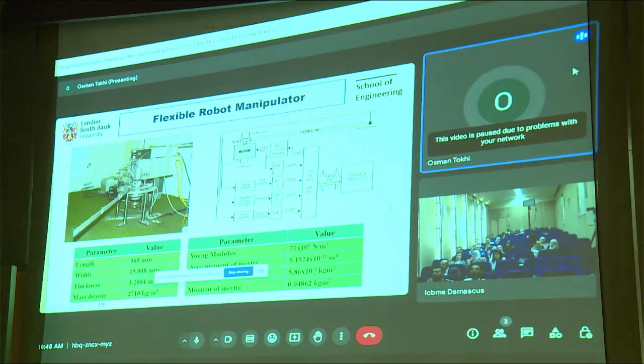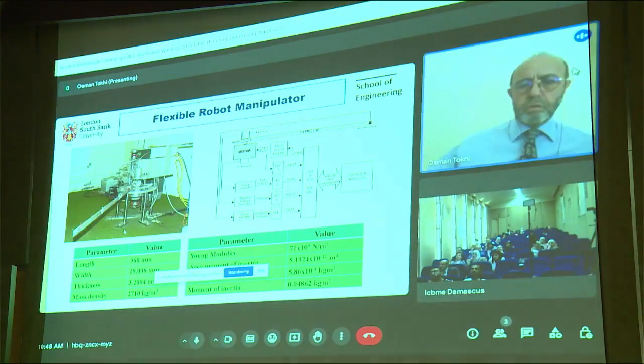Now here, this particular application is a single link manipulator. It's a robotic manipulator which moves on a single plane from a location to a desired location. There are some measurement sensors, an accelerometer at the end point, and two measurement sensors at the hub: the hub encoder and also the tachometer. That information is fed into the computer, which has an algorithm that produces the control signal, which is fed through this motor and drives the system.